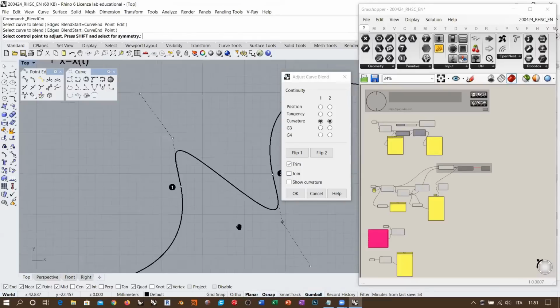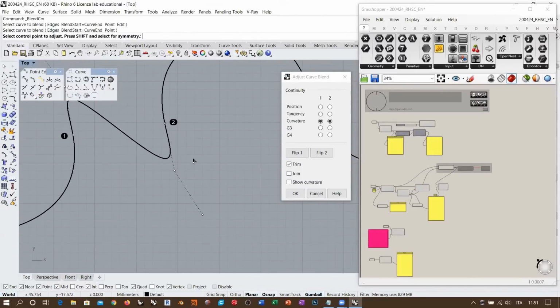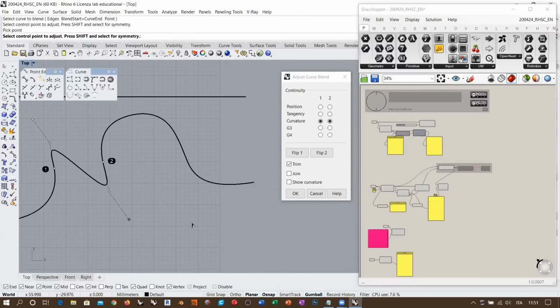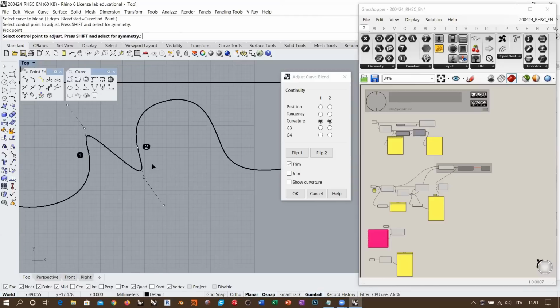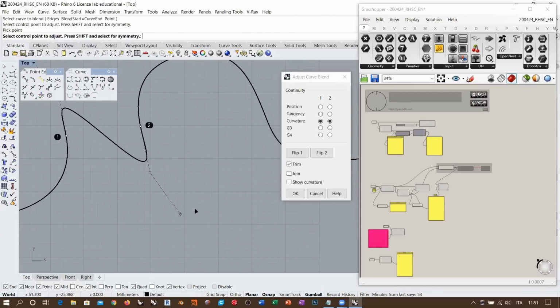And moreover, take a look at what happens, for example, if I tweak the position of these control points. If I move this, the third control point moves accordingly, because it must maintain a symmetrical set, because it needs to create an arc. But this is no surprise, right? If I move the center control point, the third one is simply symmetrical with respect to the center of a virtual curvature circle, which we will be discussing later. So you can see what the relation is between these 3 points if I move the second one. But what if I move the third one? And you see that the second one can only move along the tangent line, of course, right? So there is a strict relation between these 3 points.